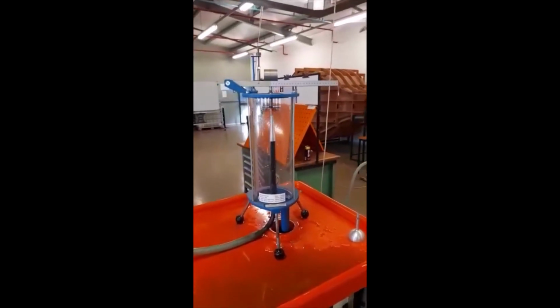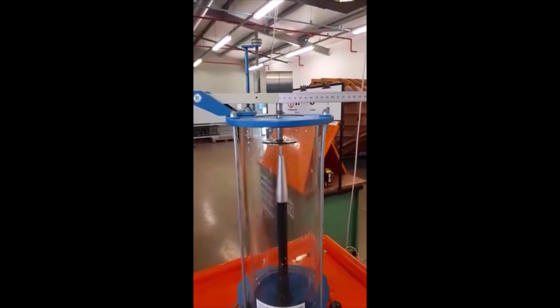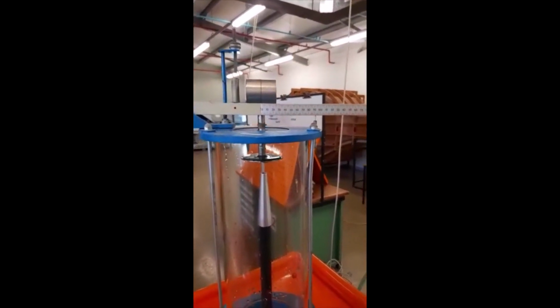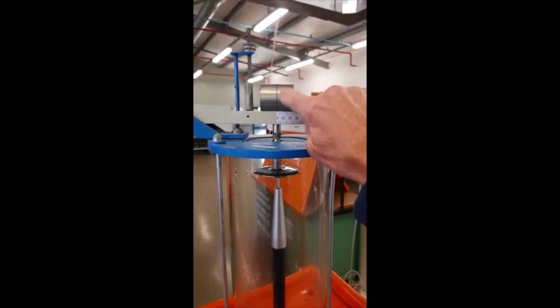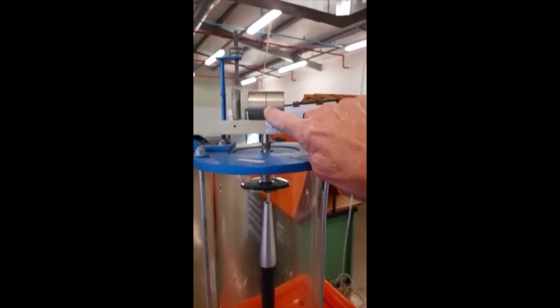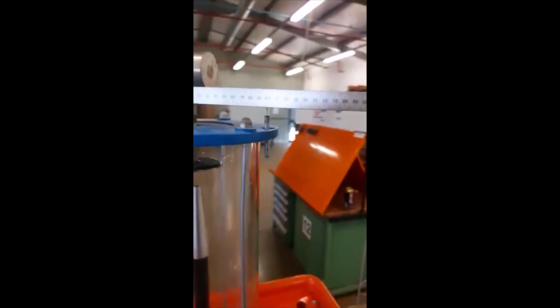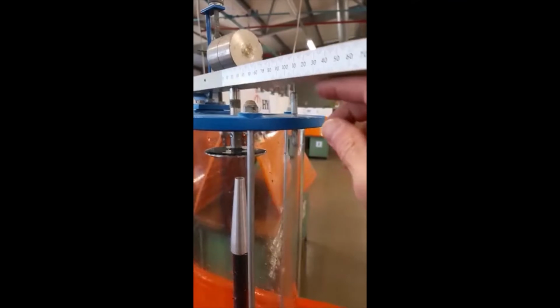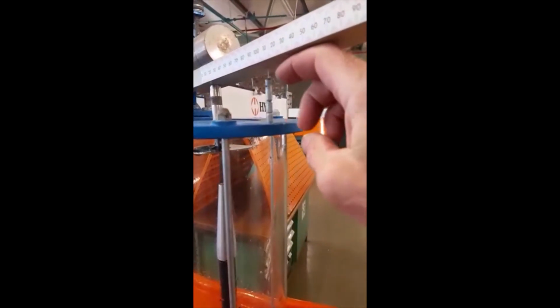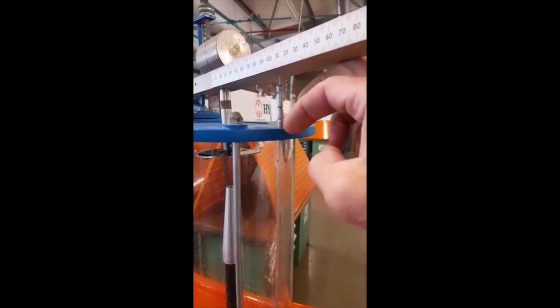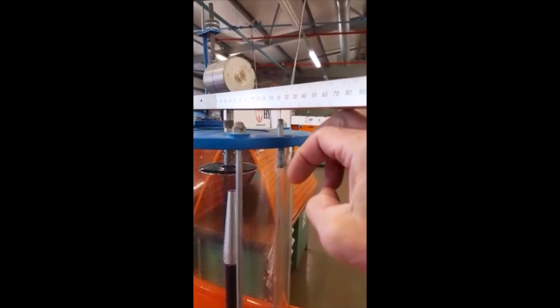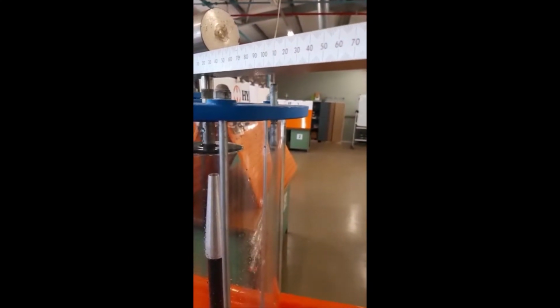Before we start capturing the data, we want to make sure that our balance arm is in equilibrium. So what we do is we put our jockey mass on 0. We use that little stripe and we put it on 0. And then we want to make sure that this tally, which has 2 notches, aligns with the top and bottom of the flange. And we use the adjusting screw to adjust.